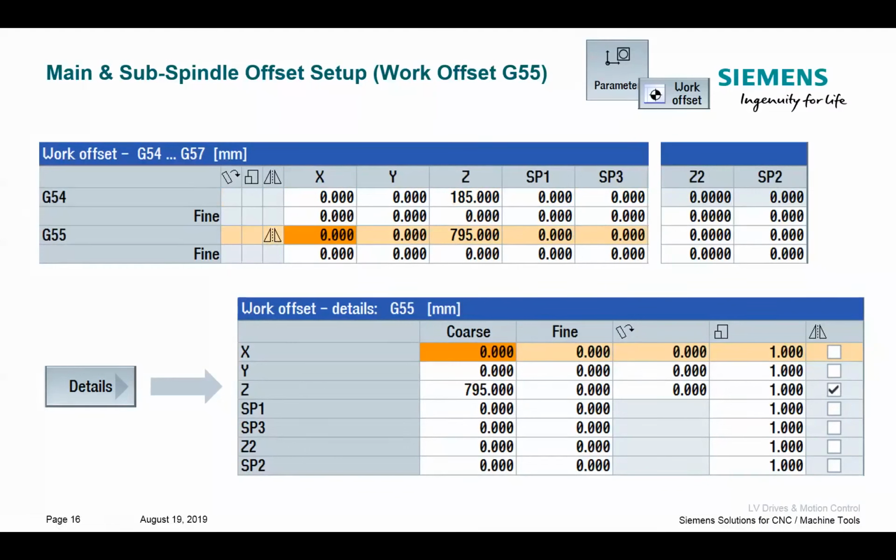So the beauty of this is whenever I'm programming the machine in a Z negative direction, I'm always going into cut, or I'm always moving towards my work holding. And the actual physical motion of the machine is going to invert itself as I bounce between the main spindle and the counter spindle. So if you have common tool paths, like for us, we have a very simple tool path that machines our boss, I don't have to reprogram the tool path.